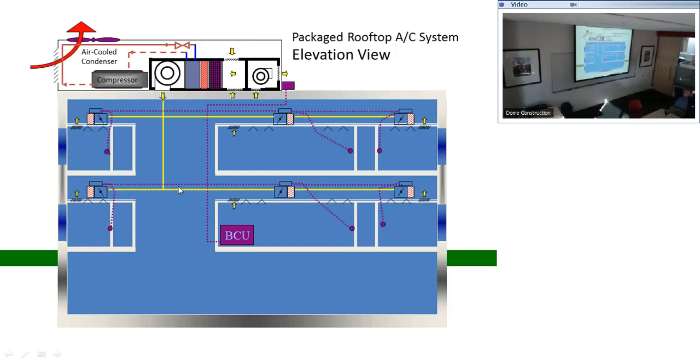The VAV part of it not only creates a lot of zones, the variable air volume component also allows me to diversify my load. We know that side of the building peaks. This is our east, so in the morning we're getting sun here, and we're not getting sun over there. So now I get to size the unit and diversify this. I know at 4 o'clock, when you're getting a big solar load here, you don't have this solar component here. So I could downsize the total part of this unit, but if I packaged it, I would have to size a little unit for that peak and a little unit for that peak. So this allows me to go maybe about 70–80% of the total capacity by diversifying these solar components.